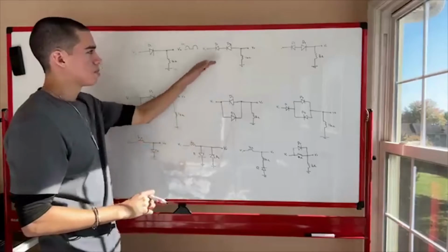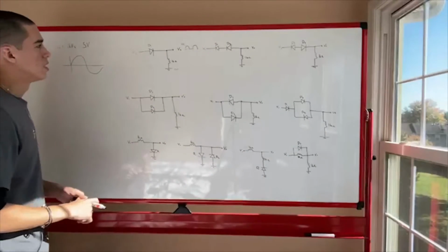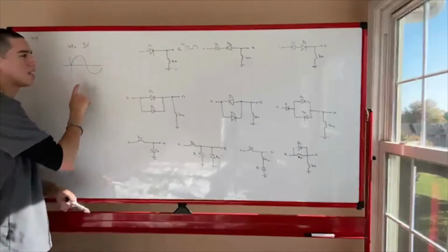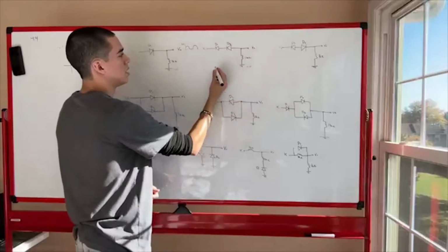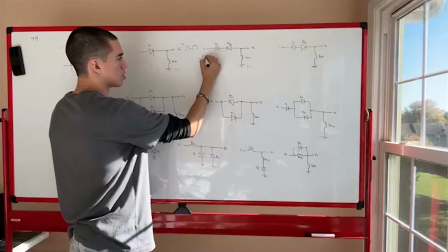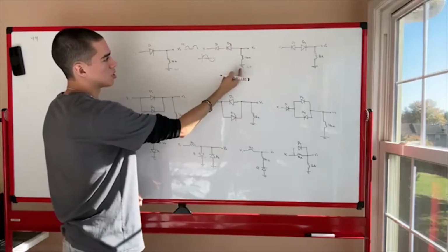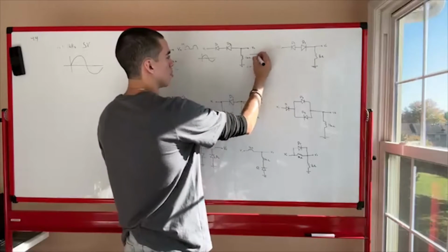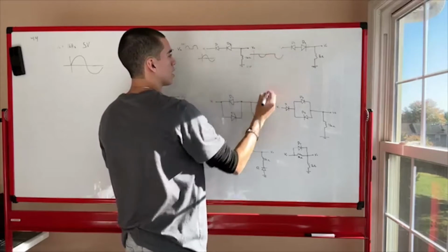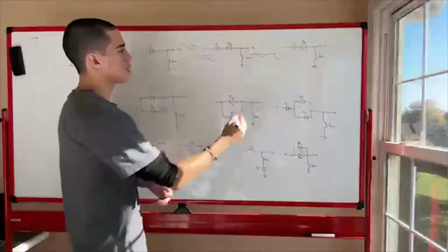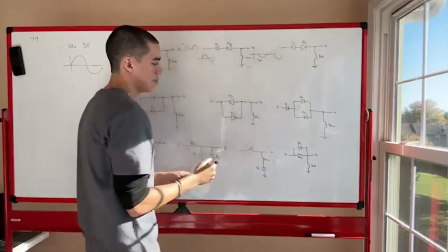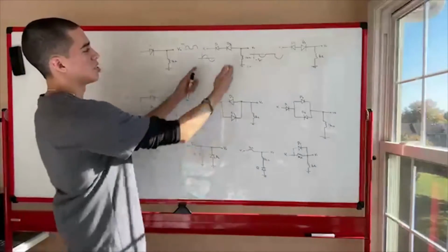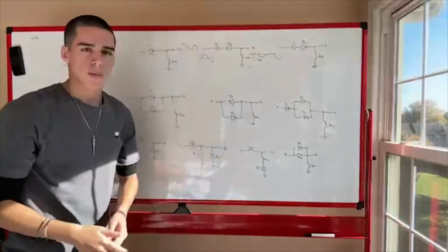So let's hop over to problem number 2. Same thing. So you can assume that these are going to be on when this voltage is negative. This would be 0, and when the voltage goes negative, this is going to be lower than this, so a current would be conducting in that direction. So the output voltage would probably be flat like that. And the peak again would be -5, because you don't have any voltage drop. If this is a short, there's no voltage drop or anything.